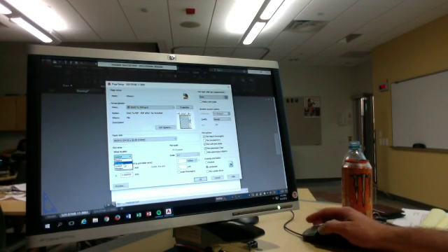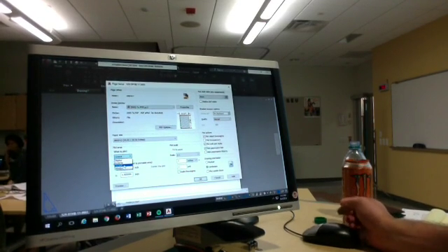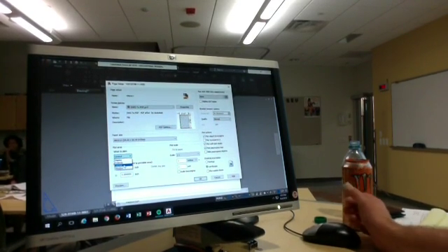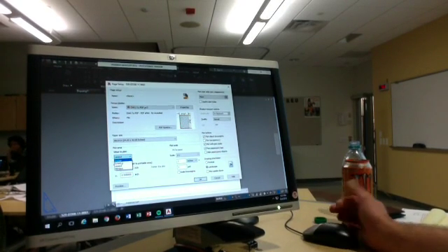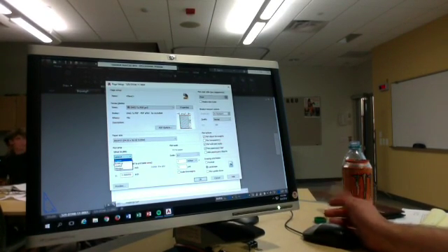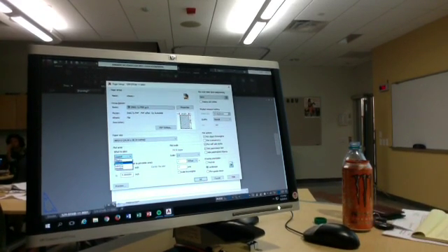Layout is something that's predetermined and built into your drawing template. We don't need to worry about that right now. We'll cross that bridge when we get to it. Display is what it sounds like. It's literally what you're looking at, but it'll fit on the paper. Extents is everything that is in that particular layout.